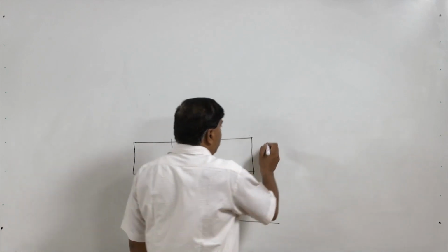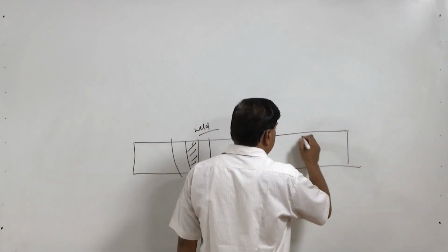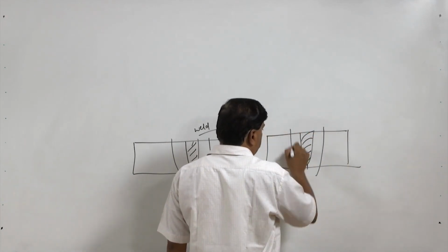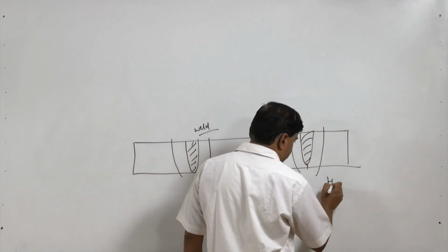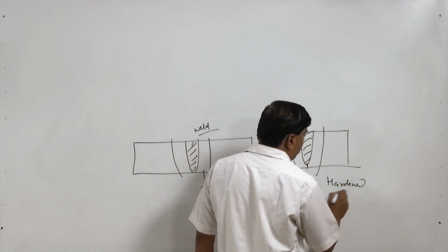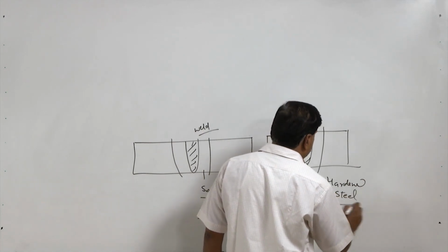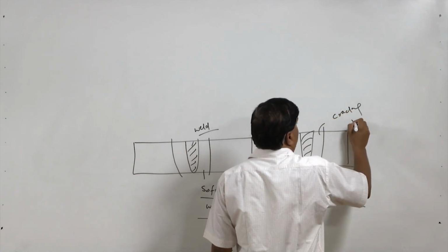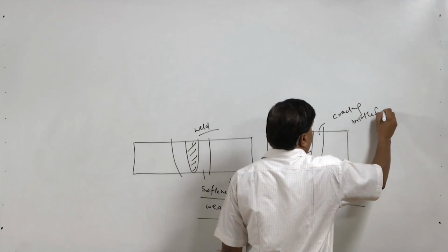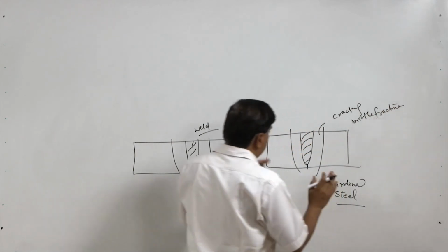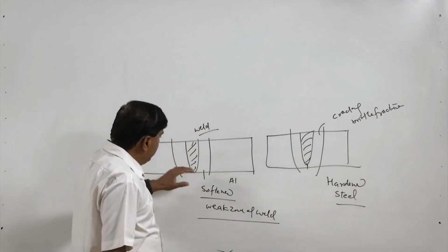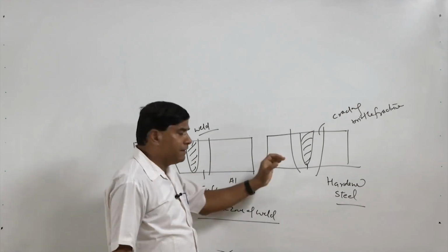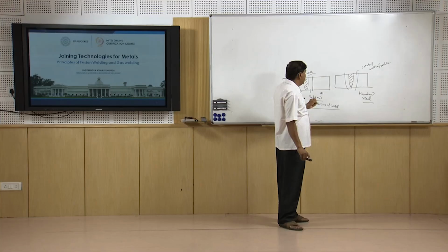On the other hand, if it is steel, then the development of the weld zone, and thereafter the narrow zone which is affected by the heat, gets hardened in case of the hardening steels. So, this hardened zone becomes sensitive to cracking as well as brittle fracture. So, in which way the heat affected zone will respond depends upon the kind of metal system being welded,